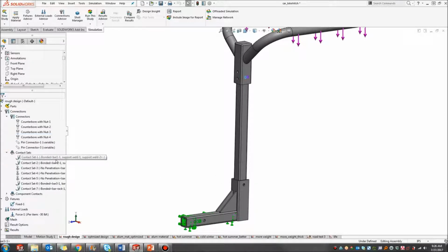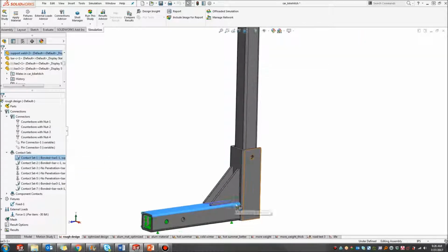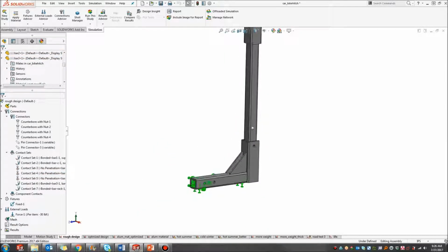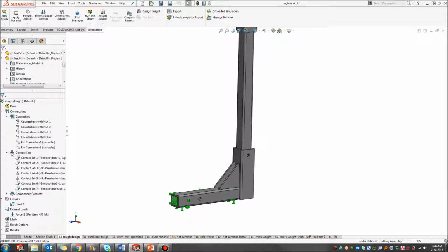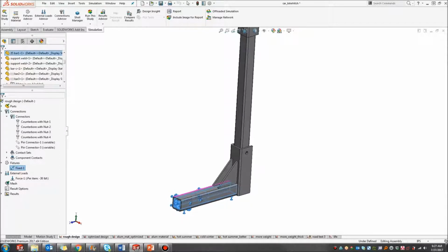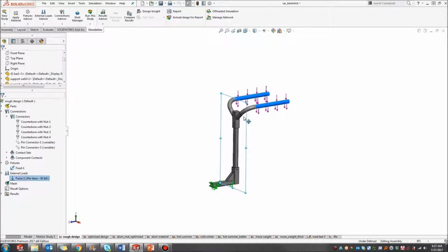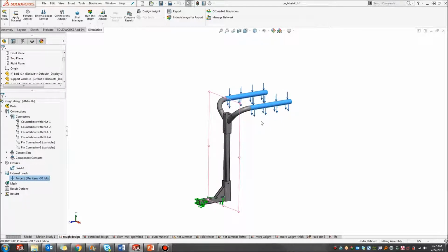Next, I've added in some context to define where the weld points are, as well as how the other components behave when they come in contact to each other. Since they are pinned together, they don't need to be welded as well. And finally, I applied a fixed geometry where the hitch would apply to the car and the load that those two bikes push on these two arm pieces.